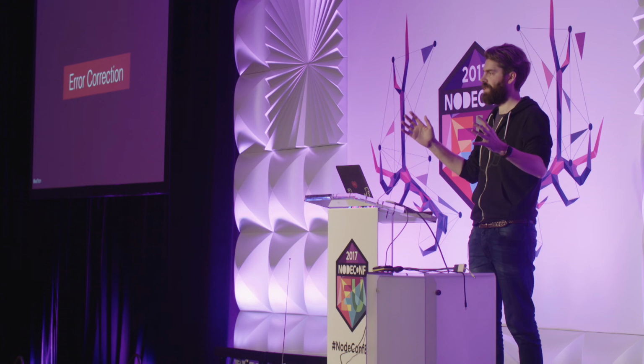now I have the theory on how to pack bits really, really tightly, but I need to error correct because errors will happen. And we all, computer people, we know that if I receive a packet with TCP/IP and it's corrupted in some way, or maybe I didn't receive it, I'm sending back a signal to the sender saying, oh, I didn't receive this package or it was corrupted, can you please send it to me again? That doesn't always work in radio. It could be that you have a sender-receiver situation where the receiver can only receive, it has no way of sending. Or it could be that the distance between the sender and receiver is so great that it's simply impractical to send a message back saying, I want to get this data again. Like, think about how we are talking to the rovers on Mars, for example. There's a long distance. The turnaround time is too big.